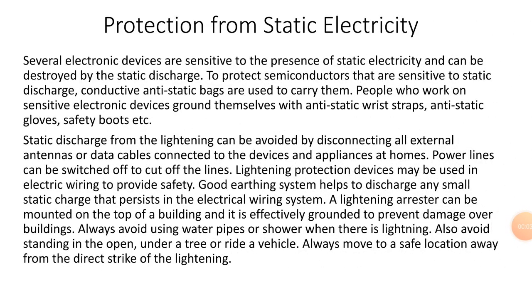Protection from static electricity. Several electronic devices are sensitive to the presence of static electricity and can be destroyed by static discharge. To protect semiconductors that are sensitive to static discharge, conductive anti-static bags are used to carry them. People who work on sensitive electronic devices ground themselves with anti-static wrist straps, anti-static gloves, safety boots, etc. Static discharge from lightning can be avoided by disconnecting all external antennas or data cables connected to the devices and appliances at homes. Power lines can be switched off to cut off the lines.